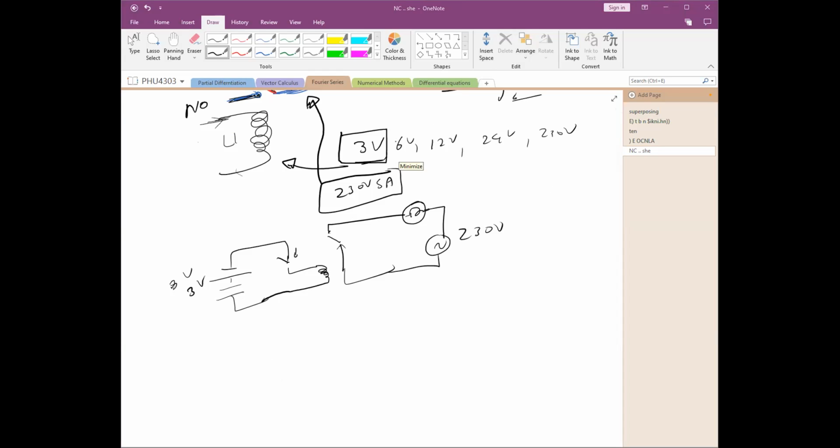Any idea? Yes, that's one thing. You can have sparks. So one negative point is you can have sparks. Another negative thing is the speed is limited. I mean, if it's a transistor or something, you can switch maybe a few hundred kilohertz, right? Few hundred times per second, maybe 1,000 times per second. But if you have a mechanical switch, you can't move that fast. It takes some time to move it, so it's a bit slow.